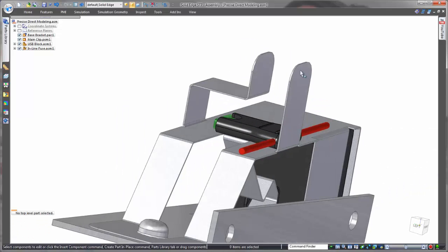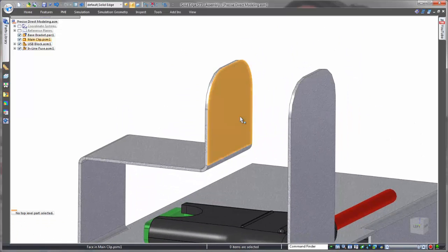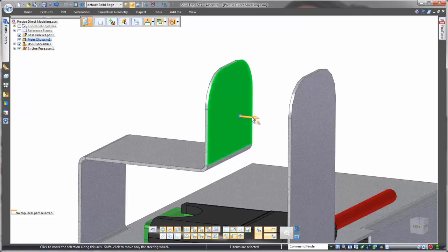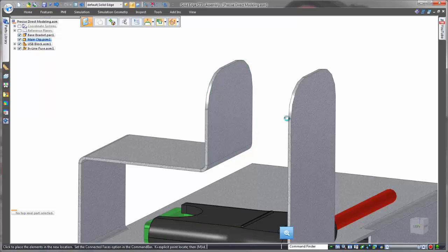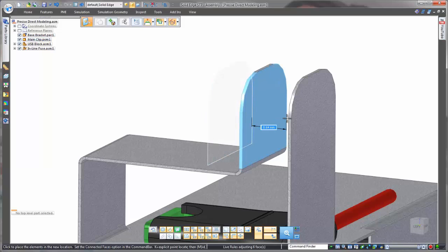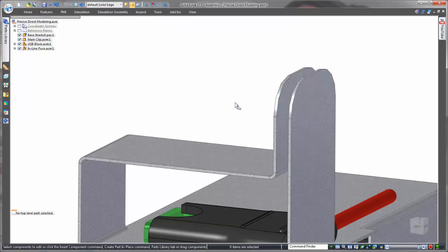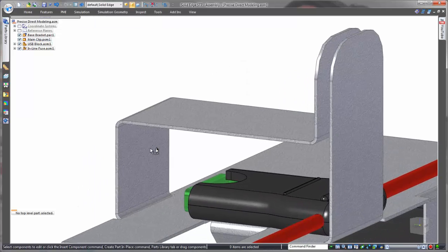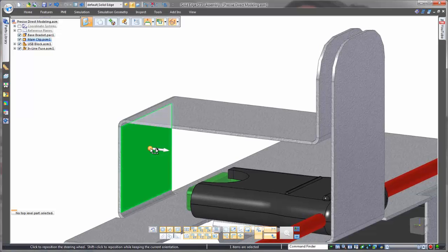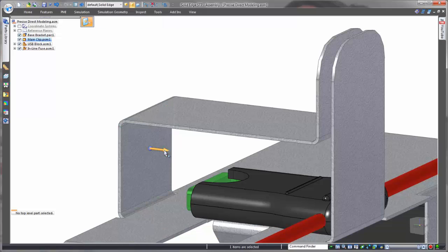I know the wire diameter is less than 3 millimeters, so using the steering wheel we can create a 3 millimeter offset from the selected face before snapping it to the other tabbed face. This leaves us with a 3 millimeter gap, precisely how we want it. This area is too wide. A drag and snap to the end of the fuse will work.